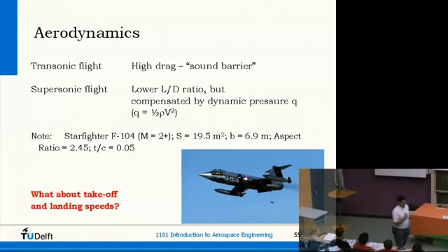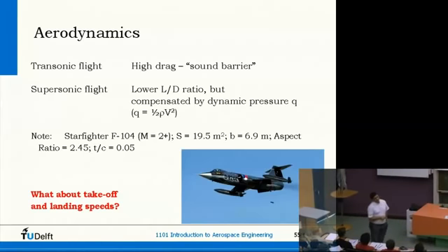The runway should be very, very long, usually in the order of 2 to 3 kilometers. Nowadays you see, for instance, a lot of new aircraft like the F-16 and F-18. They can take off within a much shorter distance, but they have indeed an increased wing surface. This aircraft has an astonishingly small one.